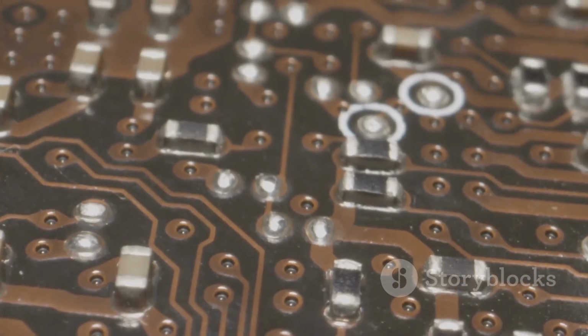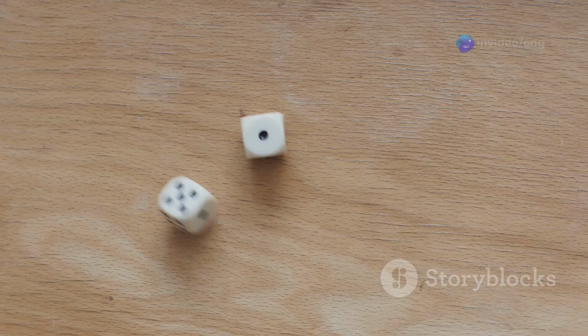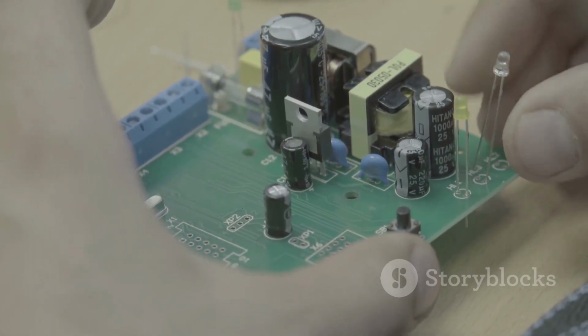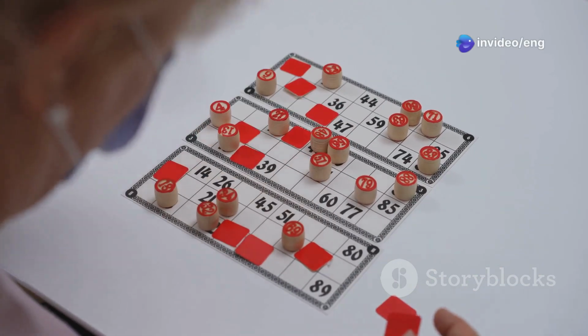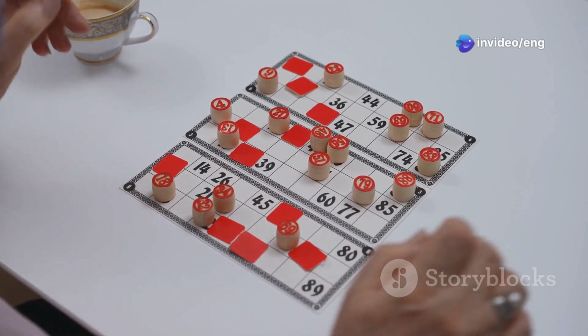There are two main types of state machines, Moore machines and Mealy machines. Moore machines' outputs depend only on their current state, like how your position on the board game depends on the last dice roll. Mealy machines, on the other hand, have outputs that depend on both the current state and the inputs. Imagine your next move depending not only on your current square, but also on a special card you draw.